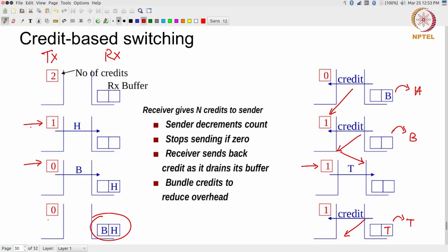It's simplifying the ACK-NACK implementation, but if you think about it really, there is no NACK that's coming back over here. There is no negative acknowledgement saying I did not receive a particular packet. All that it's saying is you can continue to send packets and at least my buffer is not full, right. So I am reducing it to the simpler case where I am only talking about the buffer part alone, okay.